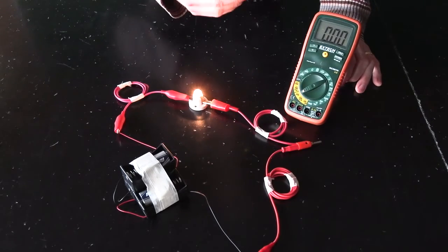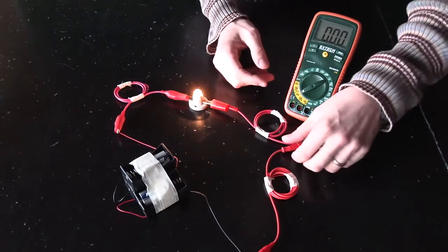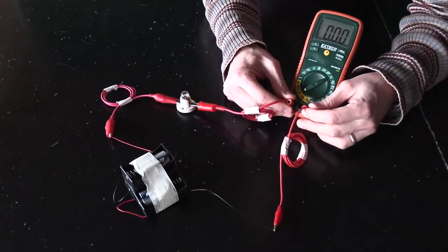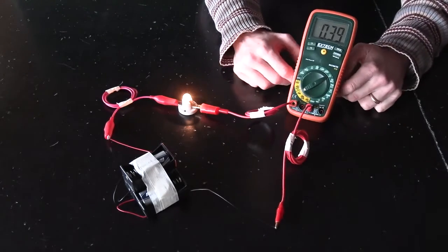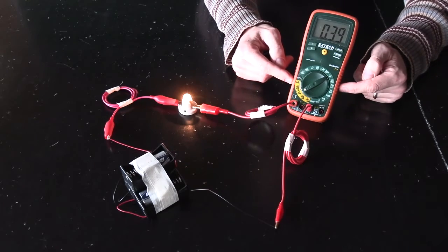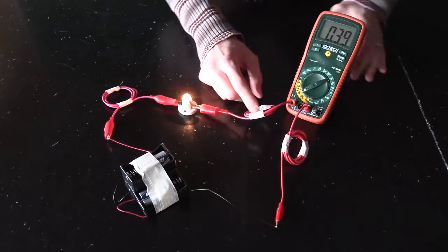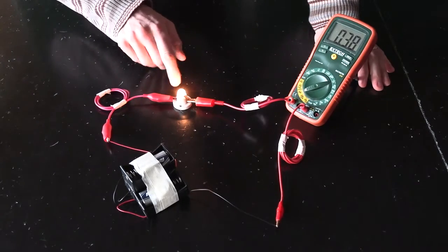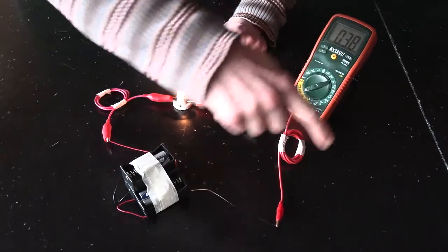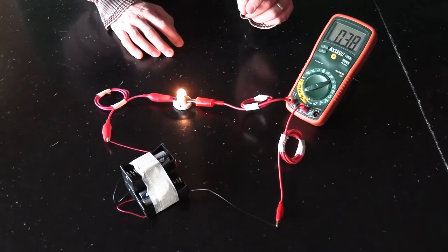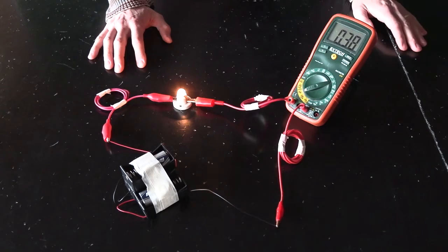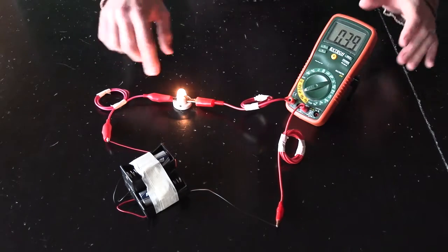In order to measure the current, what I have to do is first open up the circuit and then connect the wires, complete the connection with the ammeter. So the important thing about the ammeter is that it must go in series with the circuit. See how this is in series? It's all one chain. You put an ammeter in parallel, not only is it not the way it's supposed to work, and it won't work, but you could create damage, and I'll explain why later in this video. It must be within the loop.